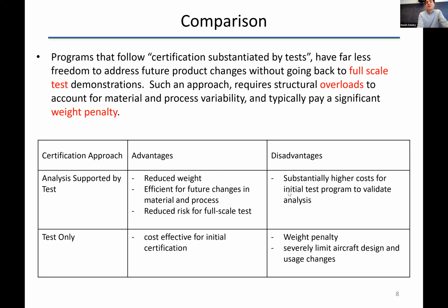So it's a trade-off between these two. And for different cases, you might choose different approaches. And typically for larger structures, larger commercial aviation, we go with this top one. But in the example I showed you for smaller aircraft, you might go with test-only certification.